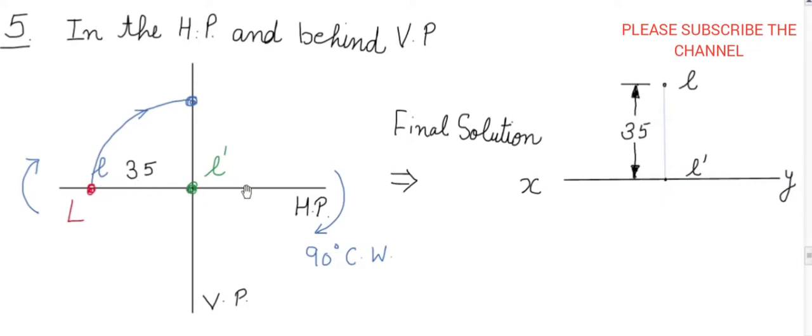What will happen applying the same rules after rotating the HP 90-degree clockwise? This top view moves onto the VP. So what will be the final solution? Draw a reference line XY, mark a point, small dot here. It shows the front view, and 35 mm above we show the top view of this particular point, and do the necessary dimensioning. This 35 mm distance will move to, okay, very easy.